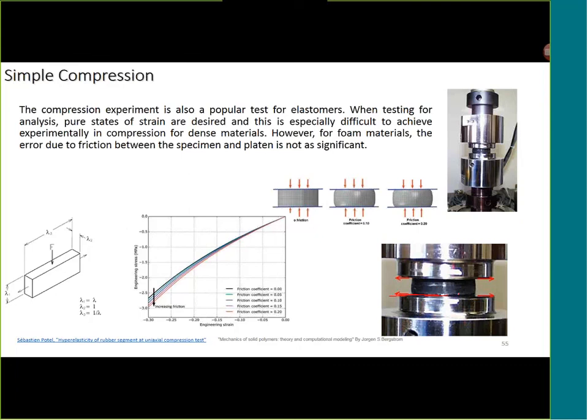It should slide like this. If it is sticking, then it will start bulging like this. Then the stress state induced in the material may not be pure compressive. So we need to avoid this. There should be proper lubrication provided such that the material expands like this. You can see that it is just a straight line here. It expands in a straight line.